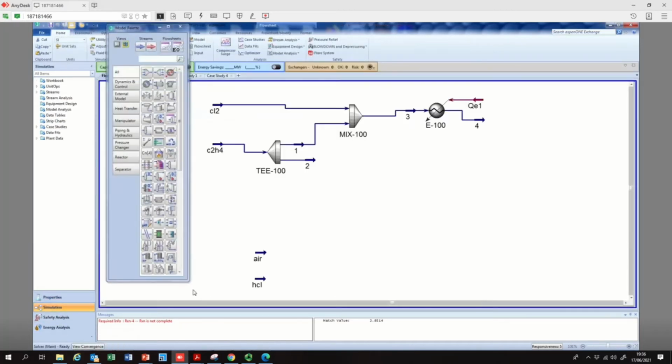This is a nice exercise in how to deal with problems. We went to the literature, took the kinetic expression, entered it into Aspen HYSYS, tried to add those kinetic constants, and checked whether we get the desired product in the product stream. Obviously no in the present case, so we switched to another idea.